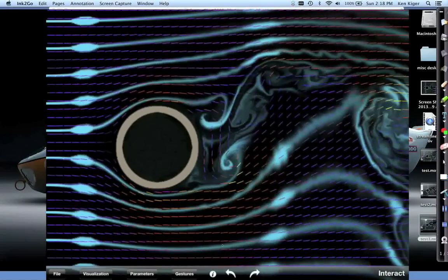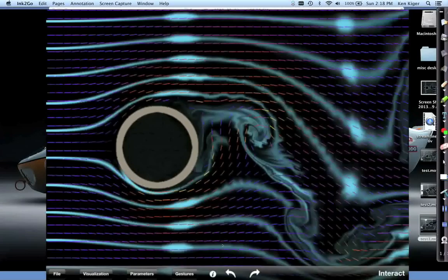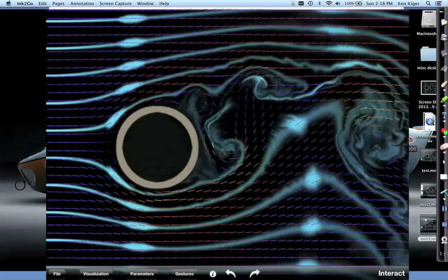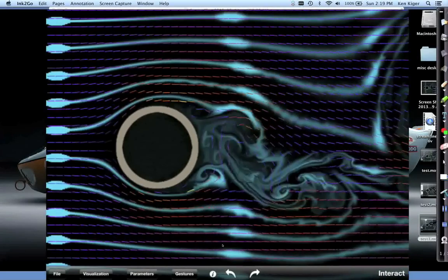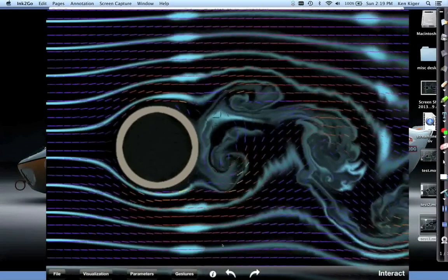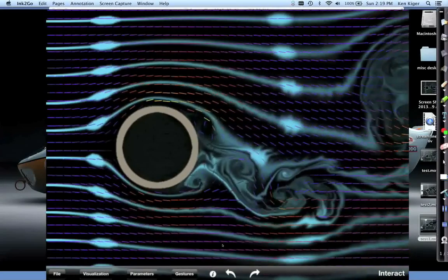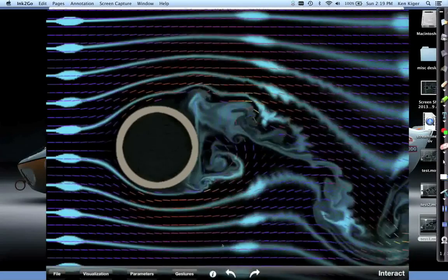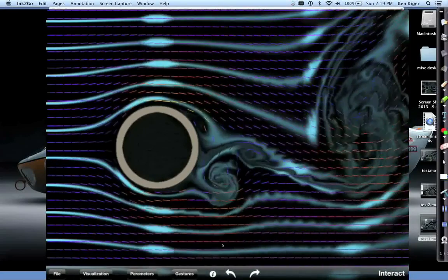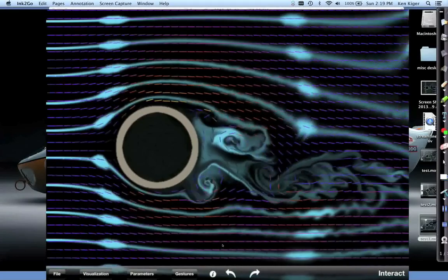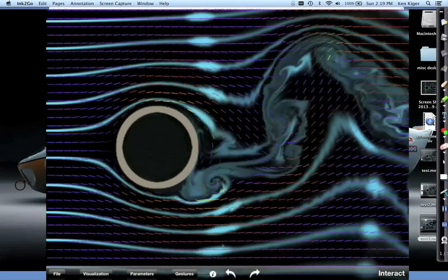What we're plotting in here, we see these small little colored line segments. These are velocity vectors, the color indicating the velocity magnitude and the orientation of the segment showing the direction that the flow is going. As we talked about earlier, this is a Lagrangian velocity field. And then we're also showing on top of that some smoke lines that are being released upstream off the left-hand side. And every once in a while a thick blob of smoke comes in to sort of give us a time reference point.